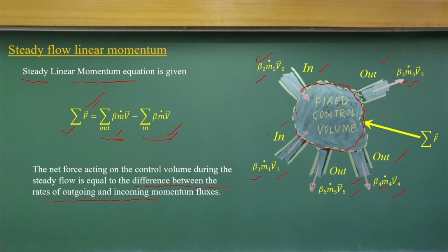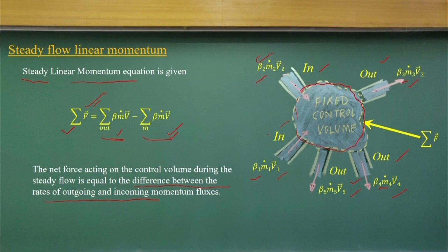In this case we have 3 outlets and 2 inlets. So, for the 2 inlets we can compute the momentum flux, and in a similar way we can compute the momentum flux going out at 3, 4, 5. Also we can consider the momentum flux correction factors, which will be different for the different inflow or outflow velocity distributions. So, we have considered the fact that there is velocity distribution variability, and that the mass flux in and out will be different.